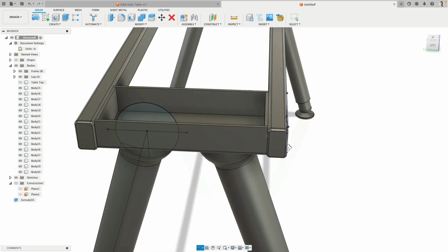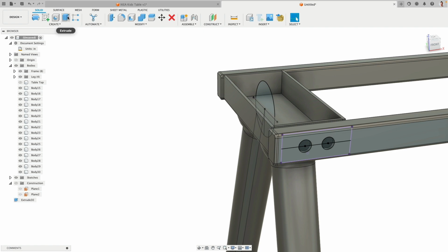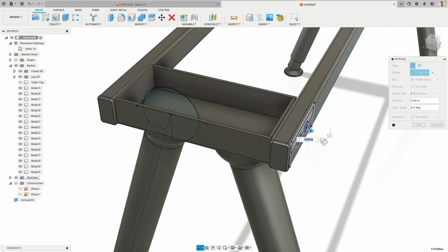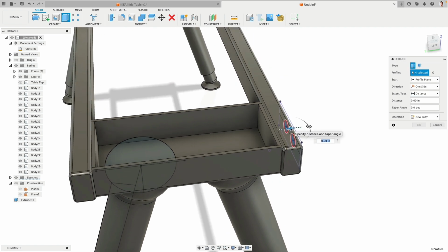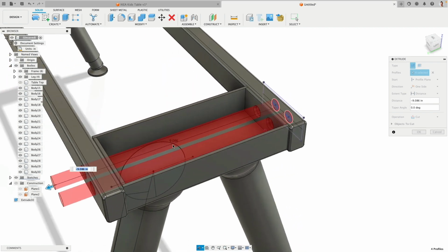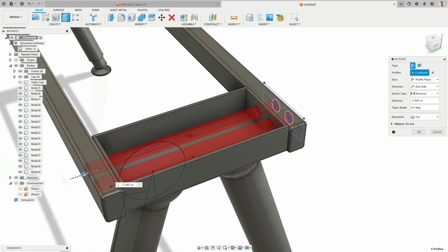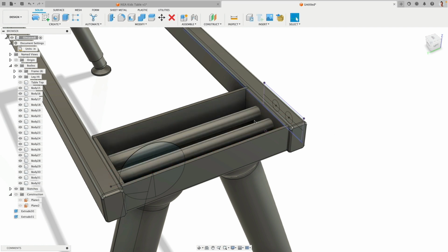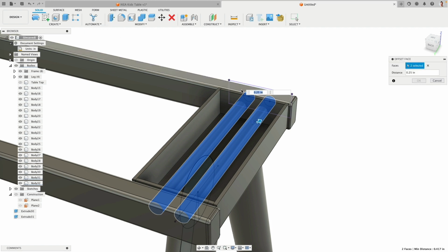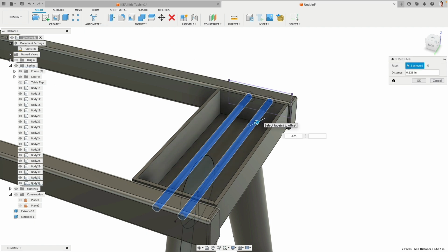I then need to have holes there too. How do I do this? Let me show you something interesting, how we can do that. So I'm cutting this one completely through, actually not completely, but till there as a new body. So that's a little trick. And then these I make actually way smaller, 0.125 there.